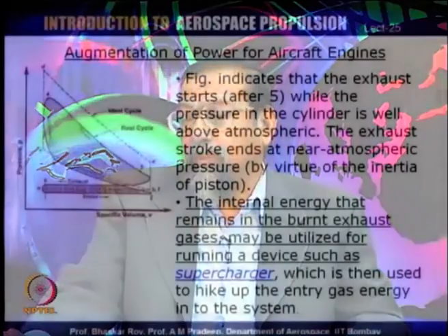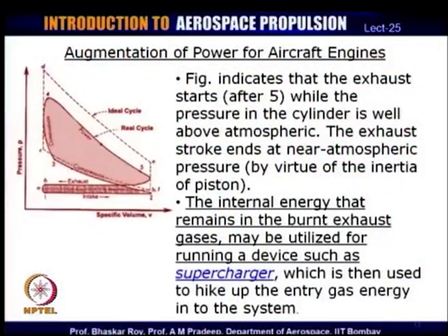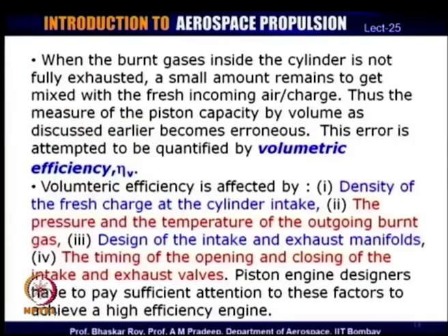and for the moment just remember that for aircraft engines you need to have this augmentation, which is normally not required in land based automobiles, but in aircraft without this augmentation procedure or without the supercharger, the aircraft would not be able to get sufficient power supply from the engine for executing its flight motions.